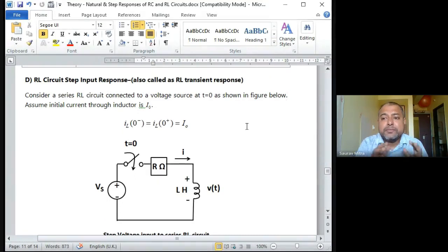So if you are not keeping the sampling frequency high, then the upper curvature part actually gets disturbed. So the higher the value of sampling frequency you take, you will find that the top curve of the sinusoidal waveform will be properly reconstructed. It is shown that somewhere around 5000 Hz sampling frequency, the sinusoidal wave is looking like sinusoidal, but the top is not very properly reconstructed. As we increase the sampling frequency, we find that the top is reconstructed very perfectly.